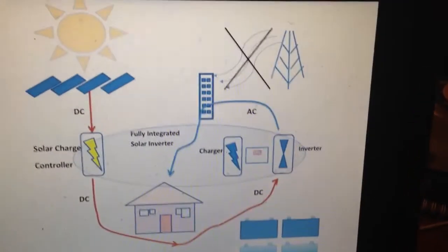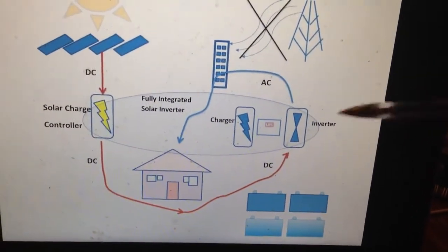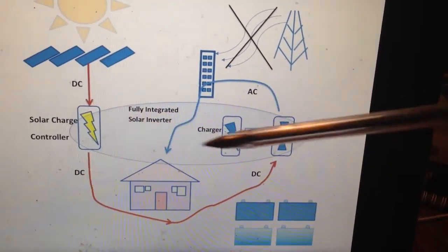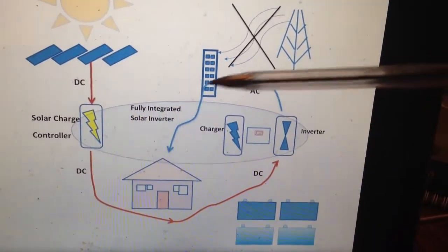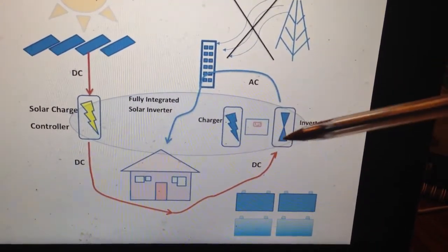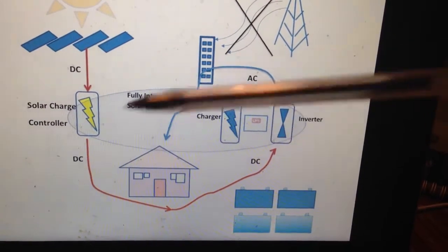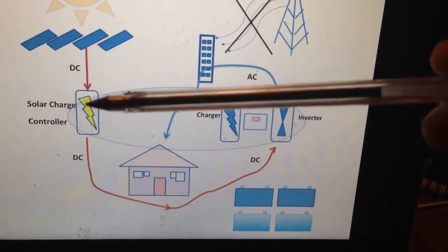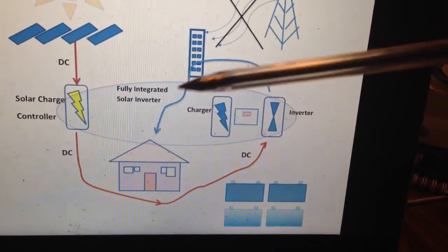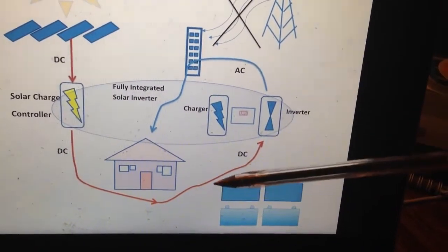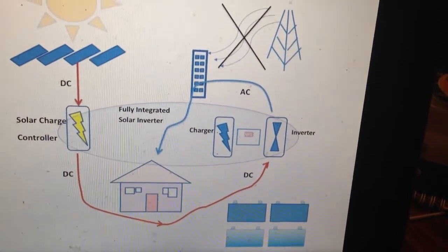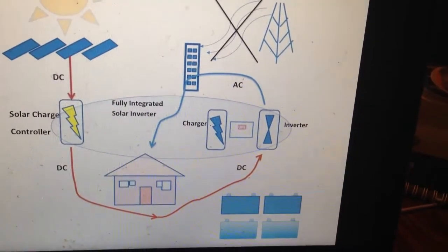And this is precisely what I'm talking about. You can see your batteries are full, there's no grid power, there's lots of sun, because it's a completely integrated system working intelligently, all the components working intelligently with each other. The charge controller part sends all this DC from the sun directly to the inverter, which just sends it directly to your house. Batteries resting, nothing to do with batteries. This is the beauty of the system.